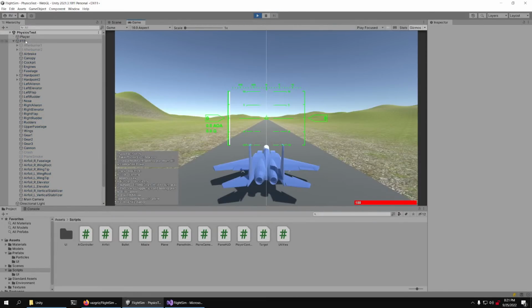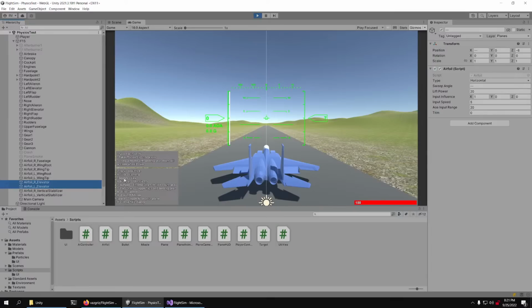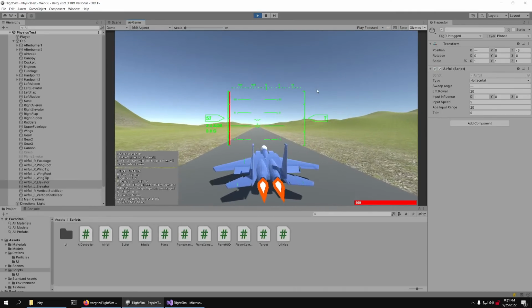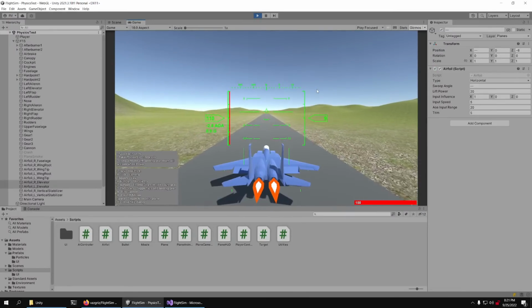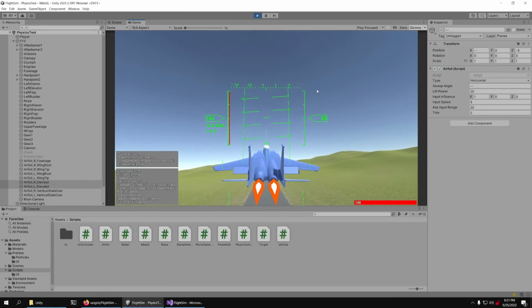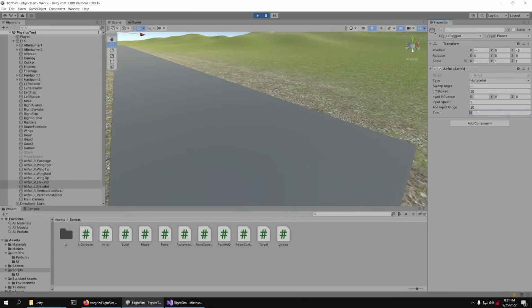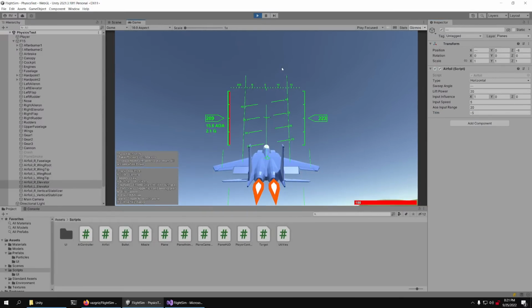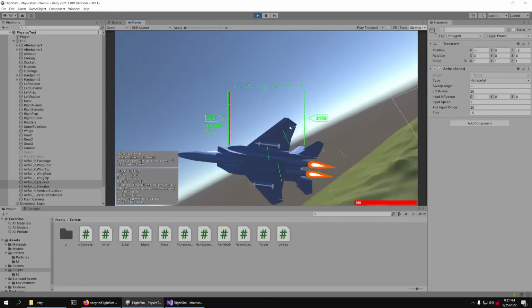But once we have the trim setting on the elevators, set this to, I don't know, 5. I don't know what this actually does. Ooh, that is a very strong trim down setting. Hold on. Let's try -5. Okay, there we go. So now the boresight, this little W-shaped symbol right here, is about 5 degrees over the velocity vector, and that's caused by trim.